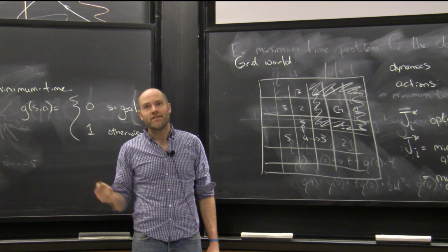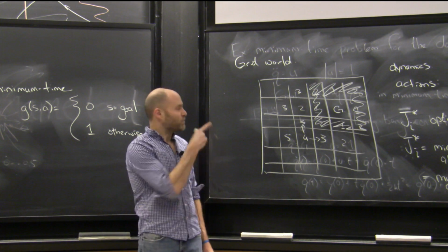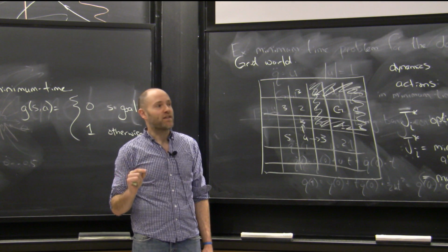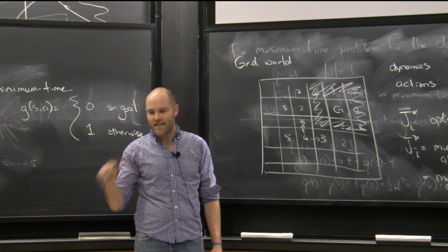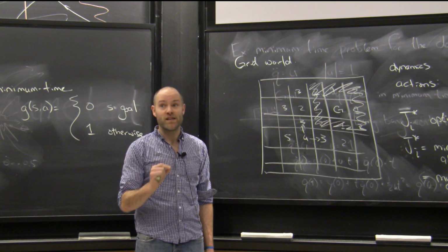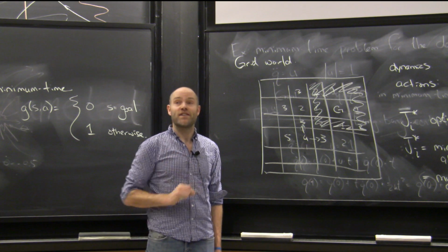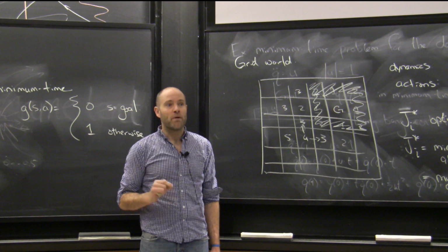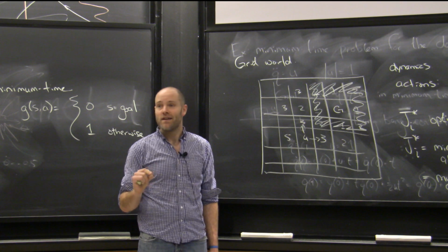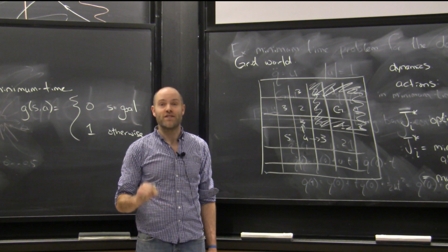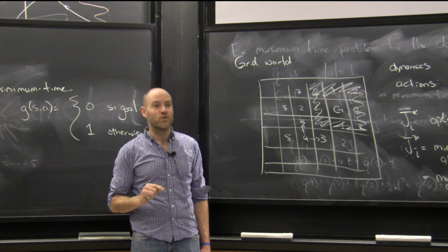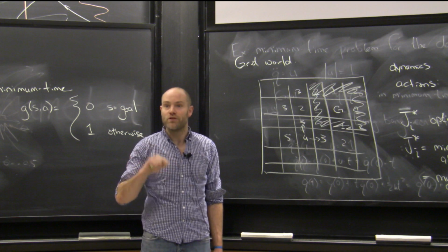Now that's a ridiculous case. You probably won't do that by accident. But remember I told you there's some subtle things about, let's say, stable in the sense of Lyapunov versus asymptotically stable. Imagine you have a system, and they certainly exist, that it's possible to stabilize in the sense of Lyapunov, but it's not possible to stabilize asymptotically. And you write a cost function that requires you to get to the origin in order to stop accruing cost. That is an ill-posed problem. It doesn't have a good solution, because you will never be able to drive the thing to 0.